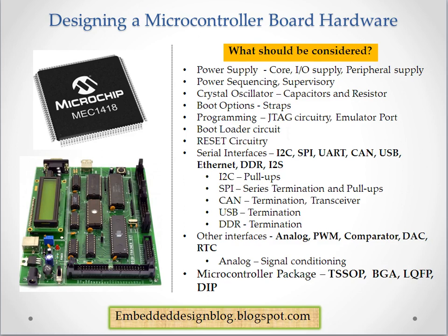A bootloader circuit is basically required if you have a serial port or USB and you want to program through it. So there will be a separate bootloader circuit that needs to be built. Most older microcontrollers have these bootloader circuits where there was an RS-232 input. Most of us should be familiar with it.